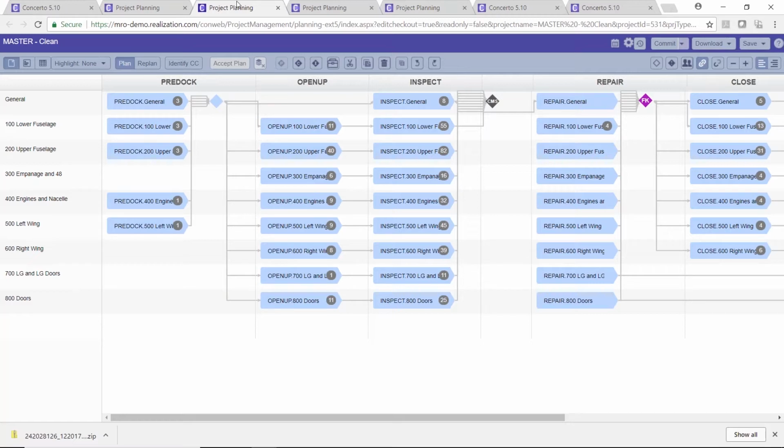What's very common in the industry is that this disassembly and inspection goes area by area and stretches out for a long period of time. In other words, I start to take apart the wing. As soon as I find a problem, I quickly want to get somebody on to start fixing it. Now my focus becomes fixing, and the disassembly and inspections on other areas like the cargo area, the cabin, the lavatories, all of this just begins to stretch out. As those inspections take longer and longer, if I find a problem, my time to fix it and get parts becomes less and less.